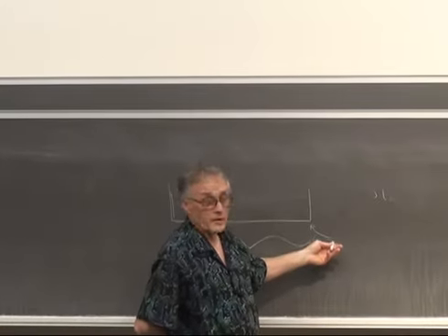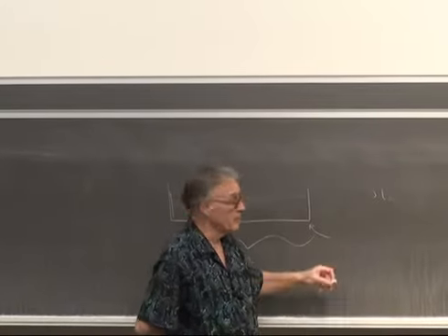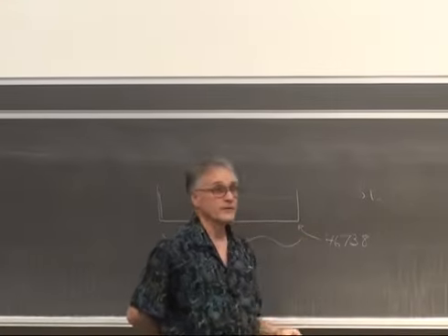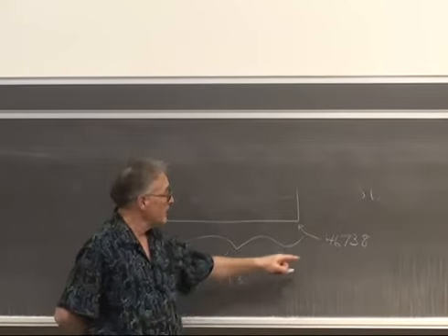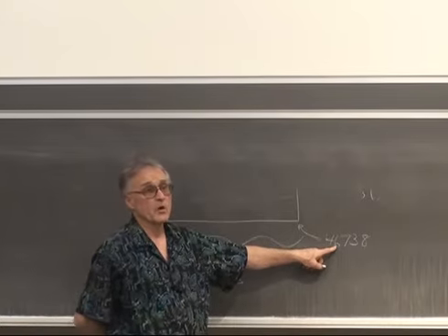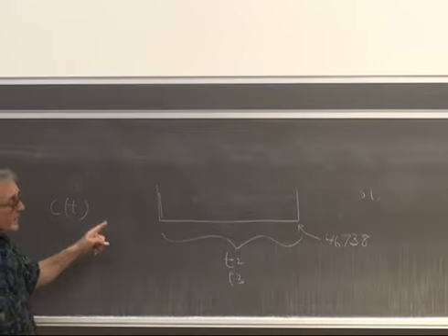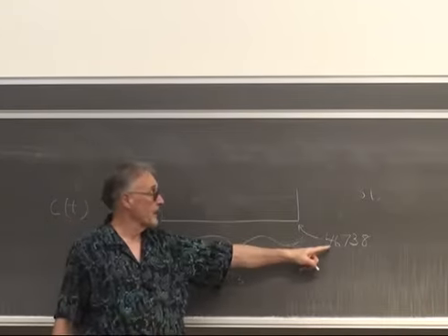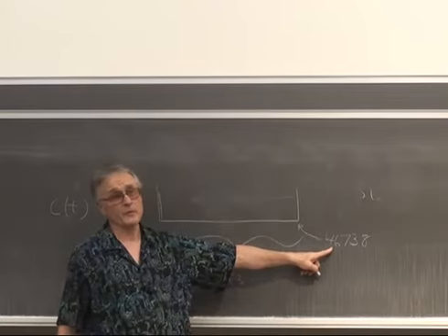So the number of counts might be set to 46,738, and that is the range you have to scale to. So if you are calculating some control factor, some control C of t, then you have to scale it so whatever the max is here scales to 46,738.